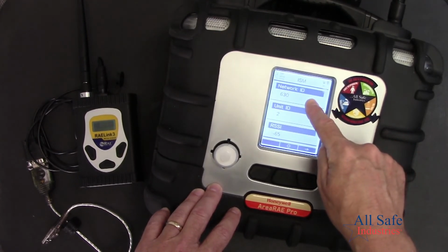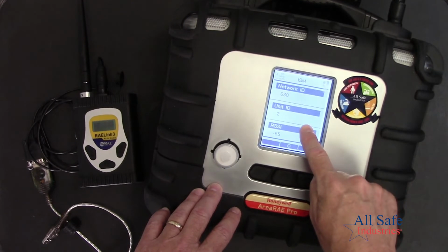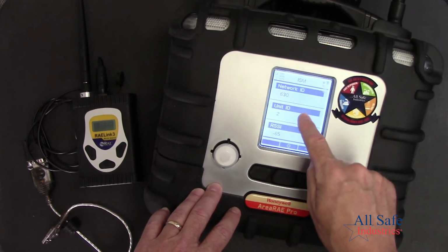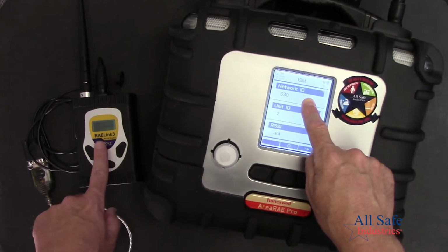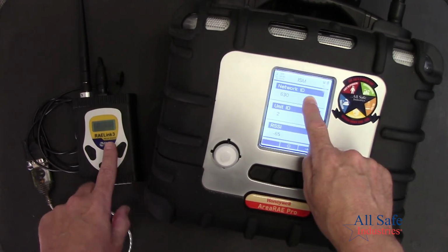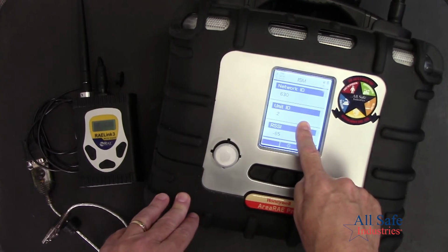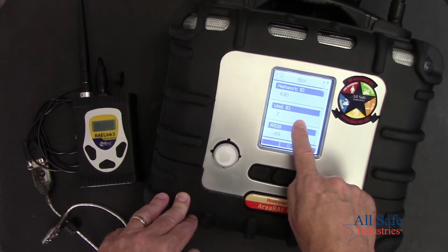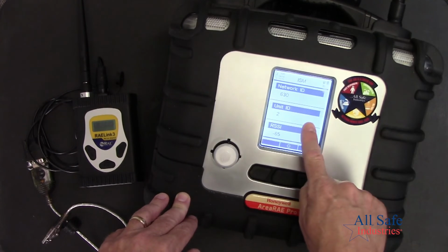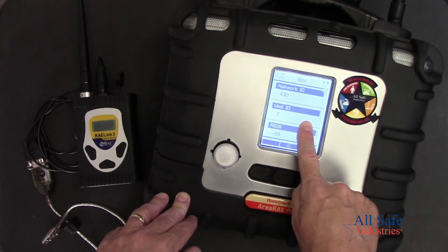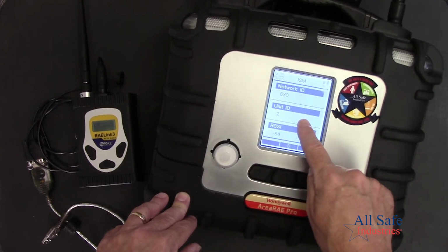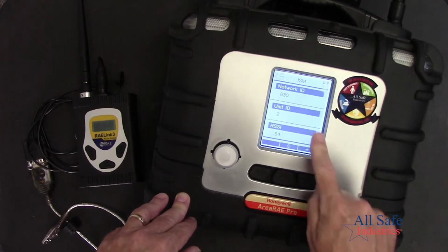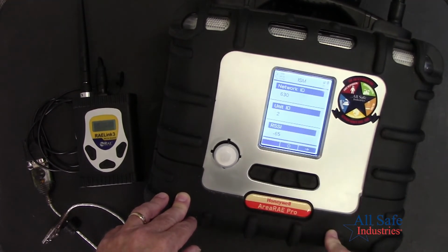And then my ISM radio is confirming the current setup details. So I'm on network ID 630, and this is unit 2. We want to make sure that our network IDs are all the same, matched up with our RAELink 3 host radio, but we want our unit IDs to be unique. Each wireless instrument on your network needs to be its own unit ID number. If you're using the same unit ID number, you could have some communication issues. So just make sure that each area array that you're connecting to your system has a unique unit ID number.